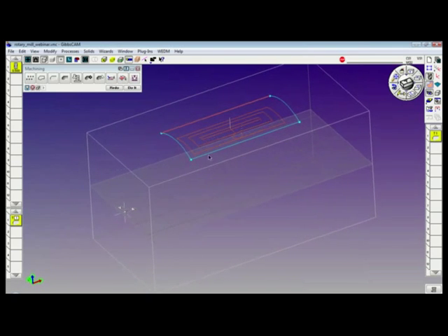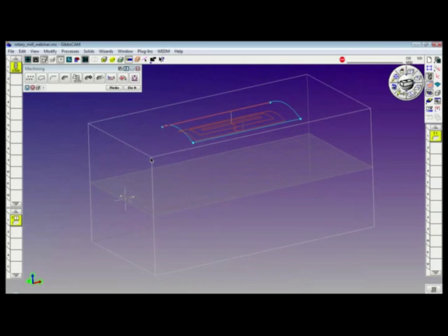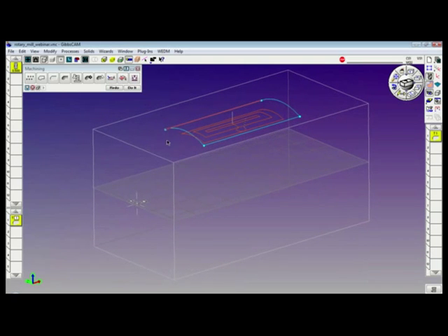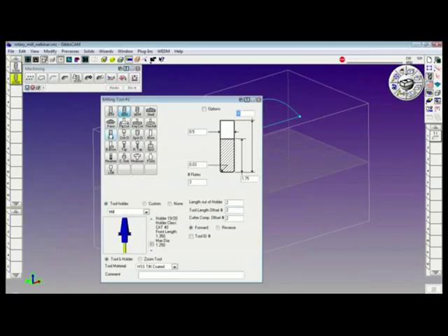What I like to do is create a series of holes. We'll make a hole by specifying a point and then doing a duplicate and rotate around the cylindrical shape. So what I'm going to do is deselect the operation, click off screen, throw away the process, which is usually done every time we want to create a new operation, and I'm going to build a new tool. The new tool will be a drill. It'll be a 1/2-inch drill, 4 inches long, 118-degree angle, default angle, and the drill will have 2 flutes.